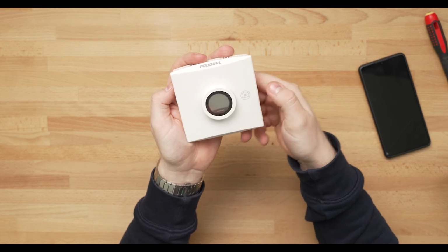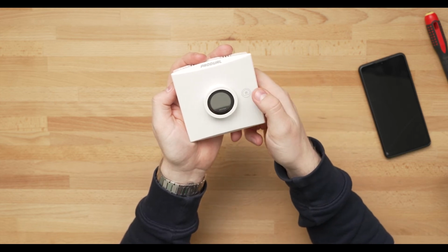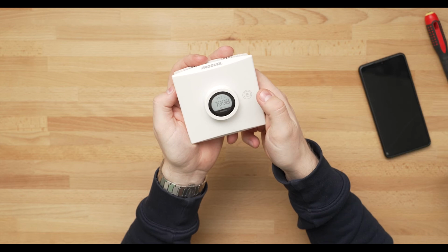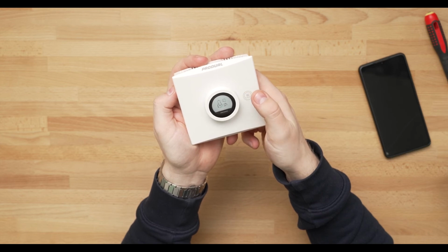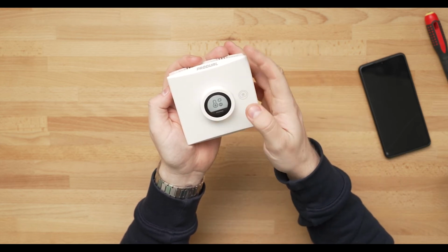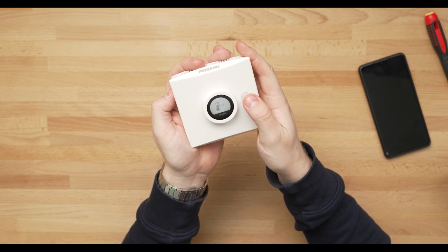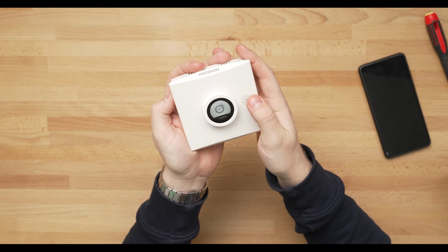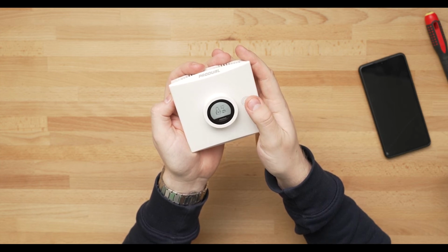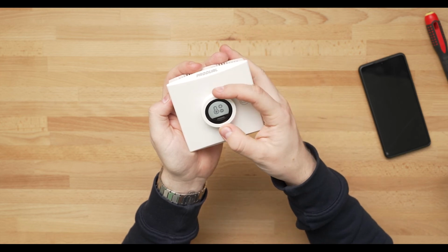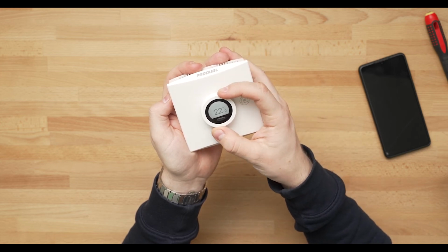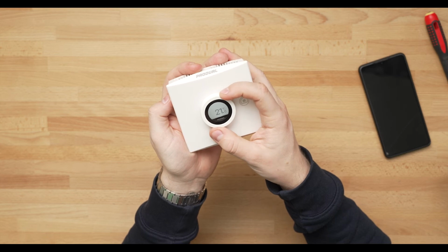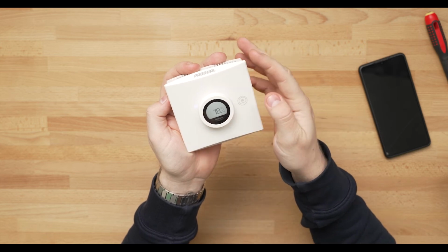There is a push button on the side, and by pushing once it activates a display, and pushing a second time we get access to these different menus inside of the AK. So here with the push button we can scroll through all the settings. Now when we are, for example, on the temperature set point, by turning the knob we can change the set point of temperature.